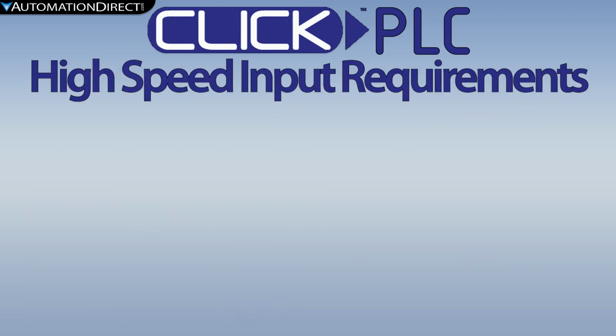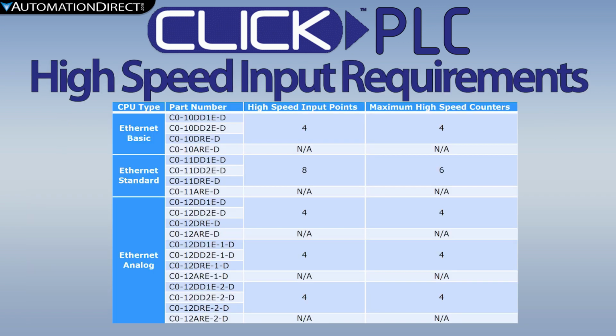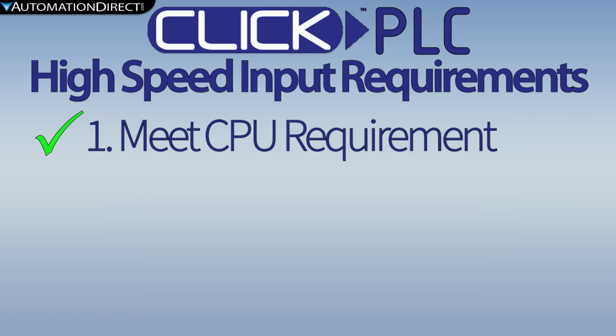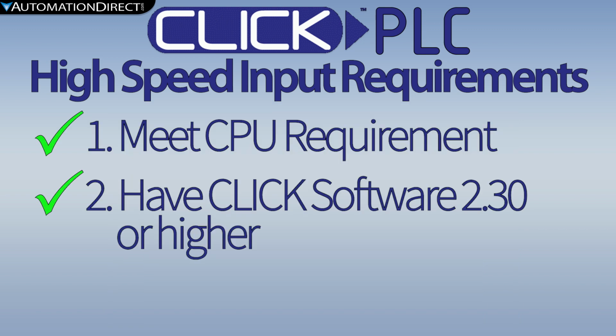To use high-speed inputs on CLICK, you must have a CLICK CPU that supports Ethernet and has DC inputs. High-speed counting is not supported on units with AC inputs. You must have CLICK programming software version 2.30 or higher and update the firmware to match this software version.